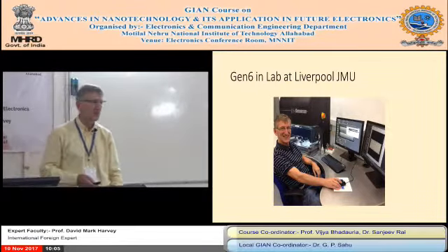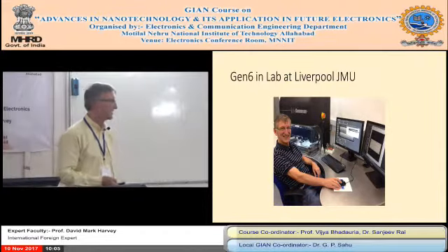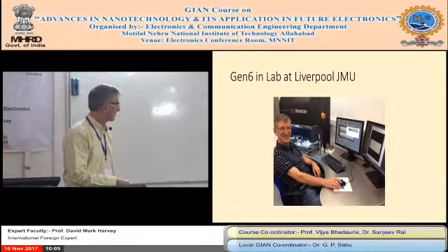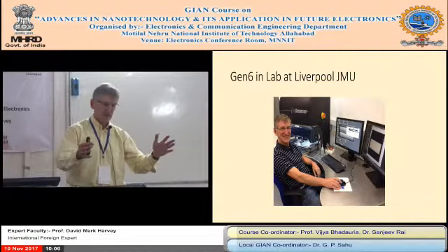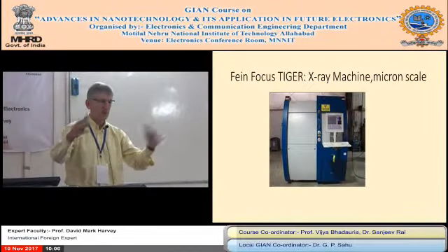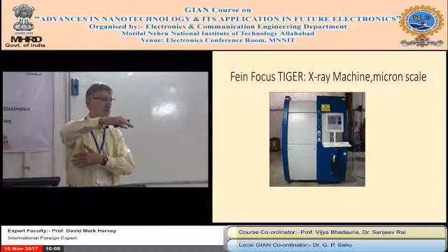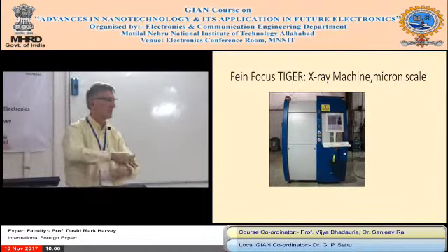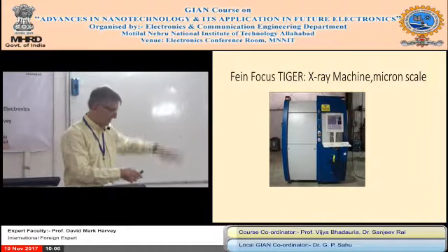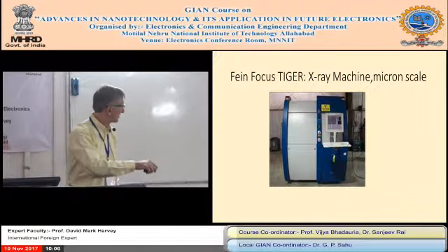So we've also got an X-ray machine, but I didn't ruin this one with my mugshot. We've got one similar to this called the Tiger. And inside this chamber, you've got about a 24-inch by 24-inch platform, so we can scan very large boards. The platform again moves in X and Y, so this chamber is quite big in the X and Y direction. And the X-ray machine is down here, sending the X-rays up and in the top.